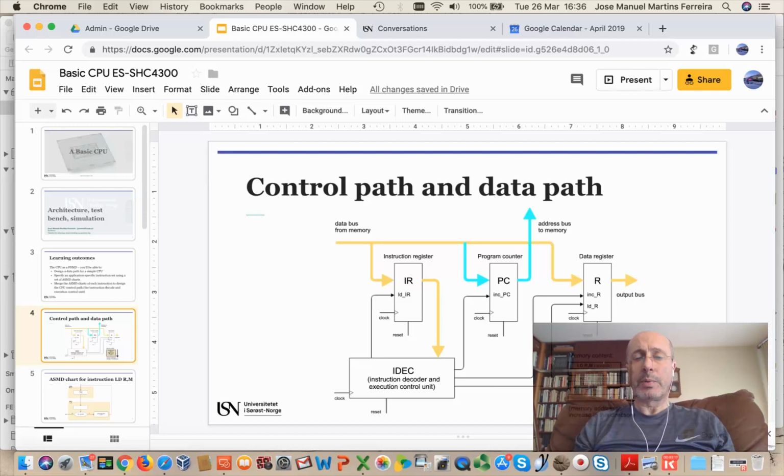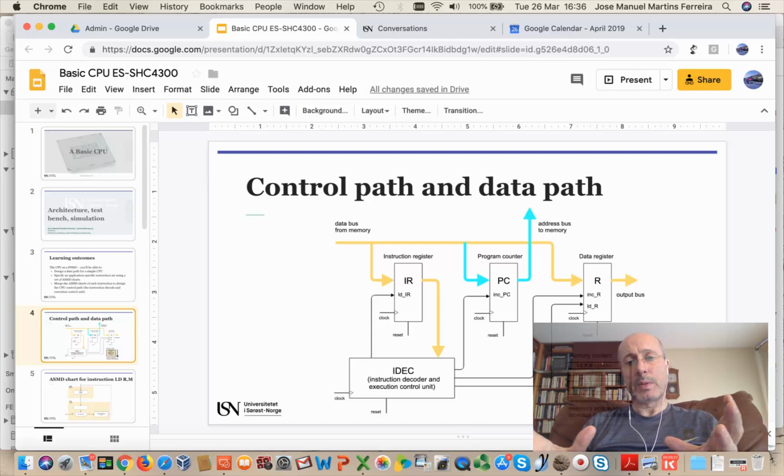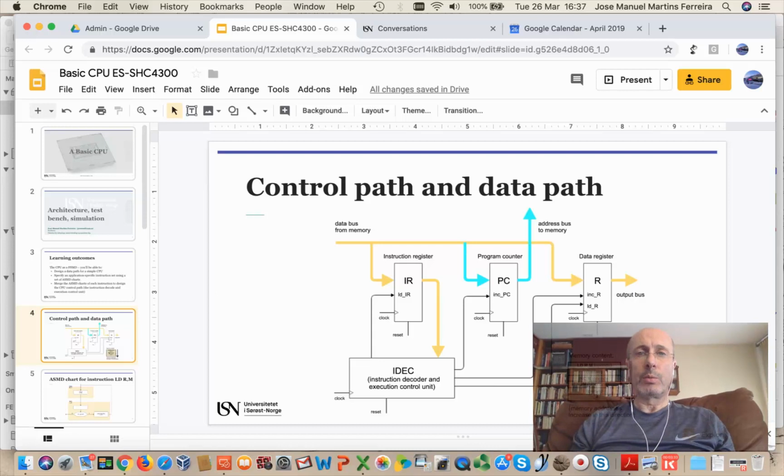And of course, jump will also be a multi-byte instruction. In this case, if we assume that the data bus has the same width as the address bus, that is to say 1 byte, then the jump instruction will take 2 bytes. Apart from this, I will also consider a halt instruction to stop the program execution.